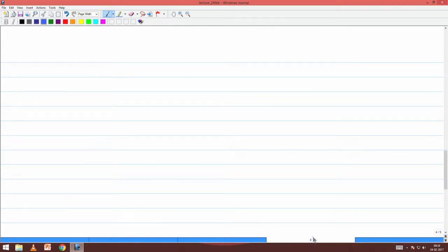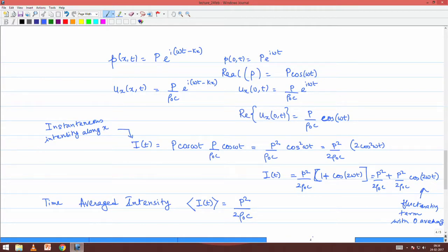What we had for the case of a plane travelling wave was that the p by u ratio, which was the impedance, was perfectly real, ρ0c. But in general this is not true. You have seen examples, like in the case of standing wave or even for the evanescent wave, where the ratio p by u will not be real.